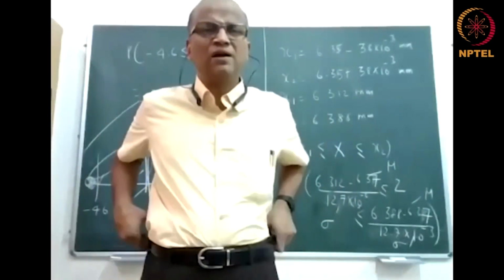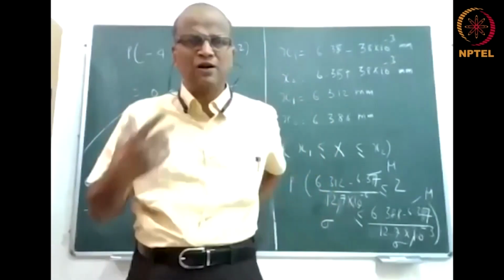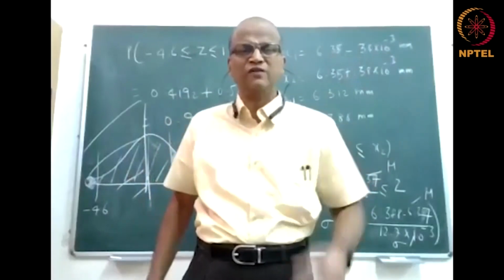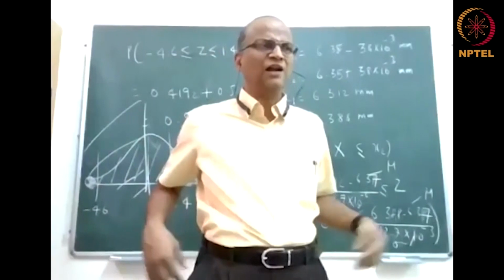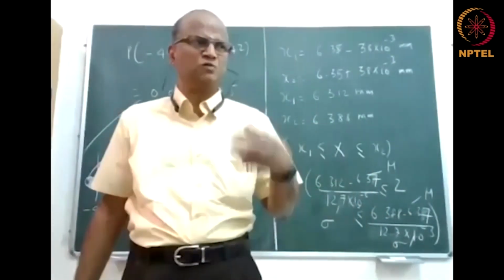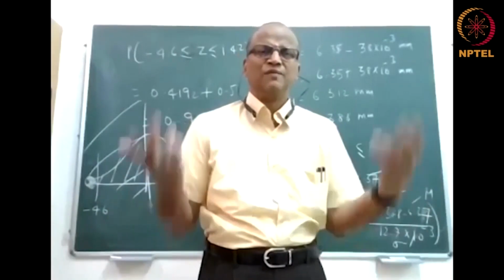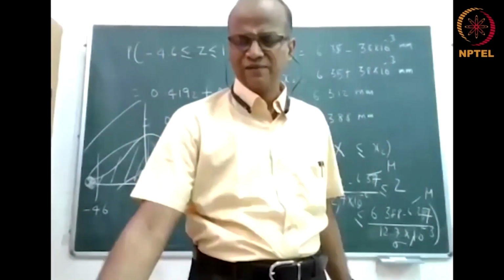You take a micrometer, screw gauge, or some other thing, or you do microscopy, whatever you want. What are the various ways of measuring a shaft diameter? You studied this as the first thing in measurement science, correct? Yes, sir. Screw gauge, vernier caliper, micrometer gauge, whatever you want to use. And then work out the statistics. Every day they may be making thousands and thousands. Then take the statistical average.